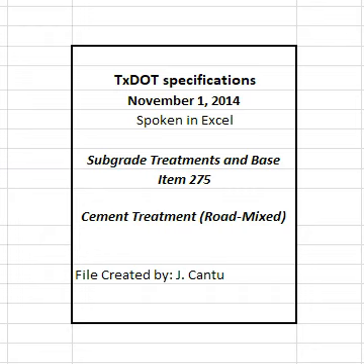4.5.2 Density control. Achieve at least 95% of the maximum density determined in accordance with Tex-120-E when compaction is complete. The engineer will determine roadway density and moisture content in accordance with Tex-115-E. The engineer may verify strength in accordance with Tex-120-E and adjust cement content to achieve the target strength for work going forward. Remove material that does not meet density requirements or rework by adding the target cement content, reshaping, recompacting, and refinishing at the contractor's expense.